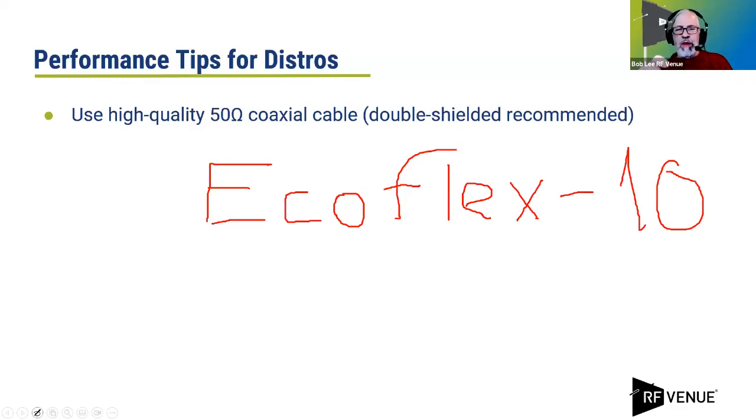That's a kind of small cable, about the size of RG8X, but it's got loss characteristics that are even just slightly better than LMR 400, and so frankly, you pay for that convenience. It's not cheaper. It's a little bit more expensive, but sometimes it'll get you out of a bind and it'll be easier to work with. Okay, so look at that.